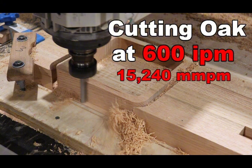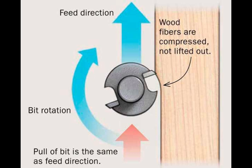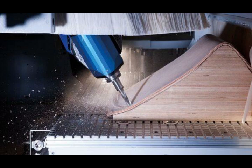Feed rate explained. Feed rate is the speed at which the CNC machine moves the cutting tool through the material. It is usually measured in millimeters per minute. A feed rate that is too slow causes excessive heat buildup. A feed rate that is too high can overload the cutter, increase vibration, and produce poor surface quality. The ideal feed rate allows the cutter to remove material efficiently while maintaining smooth motion and stable cutting forces.